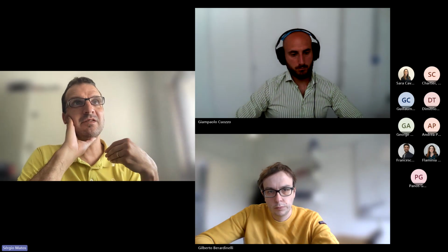You can even split the aperture because you can still do it simultaneously, but with less area for transmitting or receiving. So it would be switching from transmissive to reflective RIS, but you can actually do two subarrays, one acting as transmissive, the other as reflective, and the area of each one could be dynamically controlled. So this could be an interesting degree of freedom.